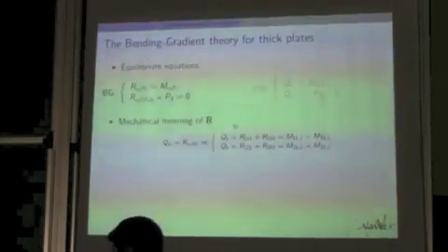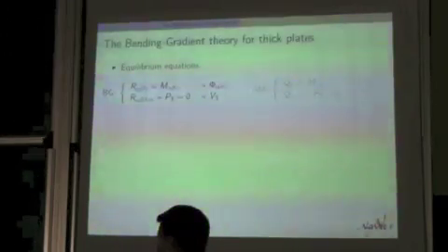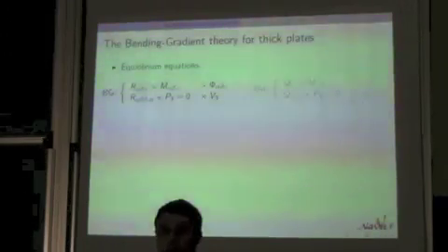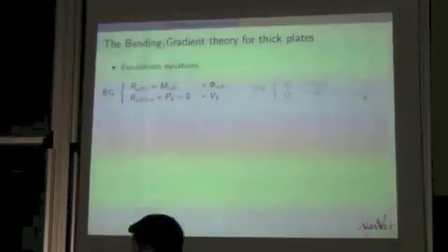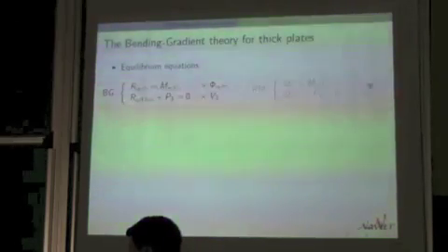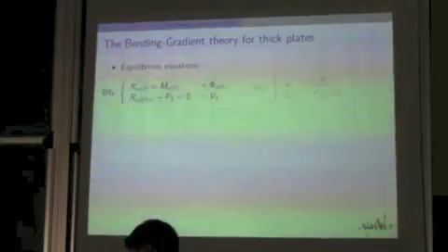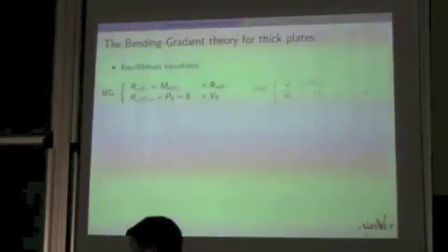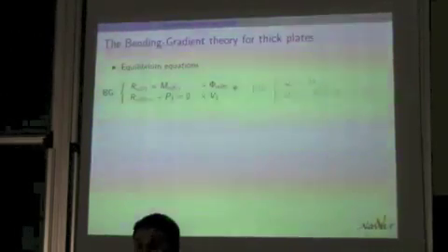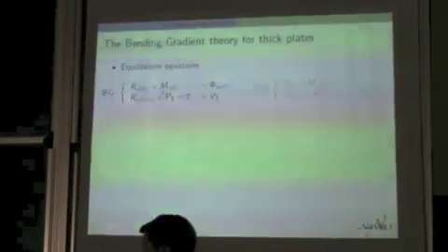Okay? Now, it's classical to dualize those equations, and it's a very classical formalism. I will do in parallel the Reissner-Mindlin approach and the bending gradient approach. Okay? So for Reissner-Mindlin, you have the deflection. You multiply the out-of-plane equilibrium with the deflection, and this relation with the rotation. Here, I need a generalized rotation, which is a 3rd-order tensor. That's all. Okay? So it's just the dual quantity of R.